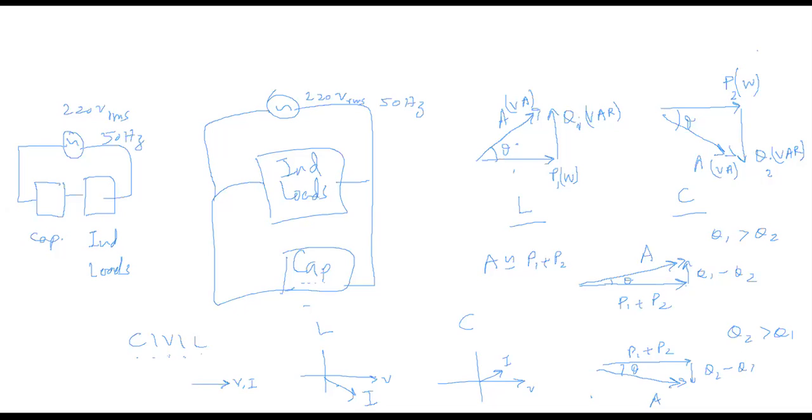Okay, so you can use a device such as a capacitor which runs at a leading power factor, and you could use it to bring the bad power factor of your load back close to unity. Instead of a capacitor, you could also use a synchronous motor, because we have just seen that a synchronous motor can also be run at a leading or a lagging power factor. So this is exactly what I'm asking you in this complex engineering problem. Let me flash it.